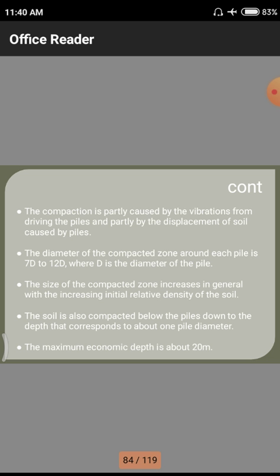Okay, this is the main point. That means whatever the pile depth we are doing, after the pile depth is over, we need to compact the particular soil to arrest the water entrainment into the soils.